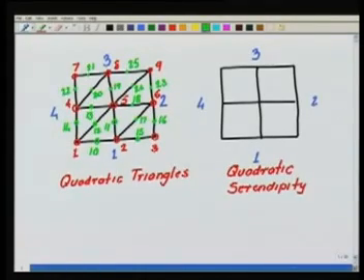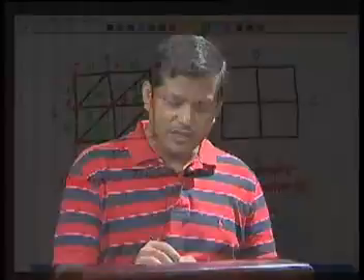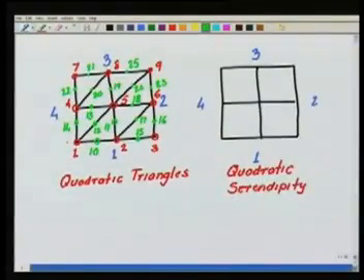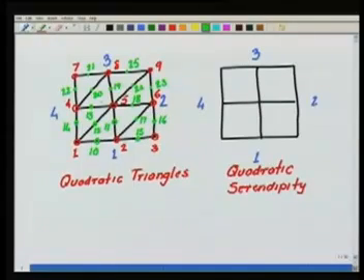So as I had discussed last time, the corner nodes of the elements of the domain, the vertex nodes, will be given the degrees of freedom first. That's my convention. It has its advantages. After that we'll name the side degrees of freedom element by element. So first I go to the first element, number the degrees of freedom corresponding to that element, then the second one, and so on. So here I have 25 degrees of freedom.